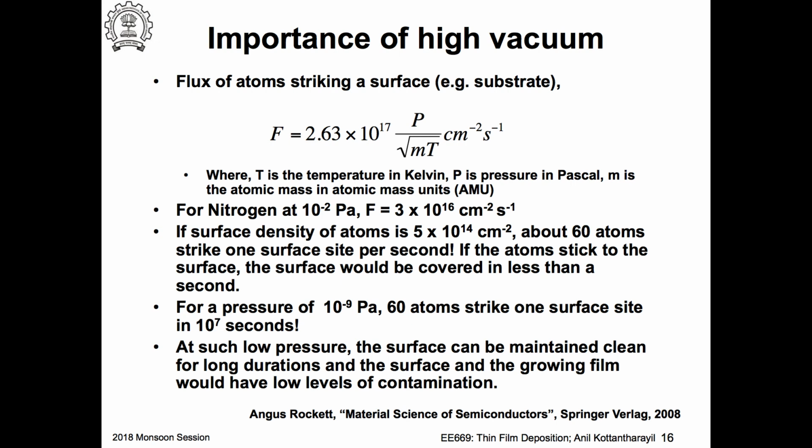So this means that if I have an MBE system and I clean the wafer and load it, but still during the process I contaminate the surface, they do some in situ cleaning in MBE systems, but then you can retain the pristine surface for very long time. So that's very important for many applications. I think the last point we already discussed.